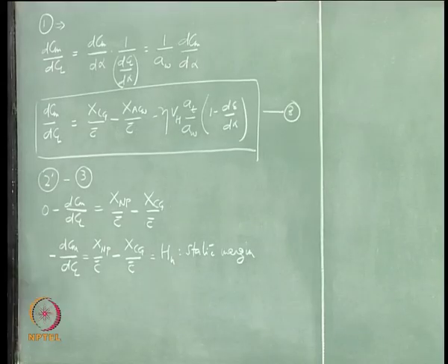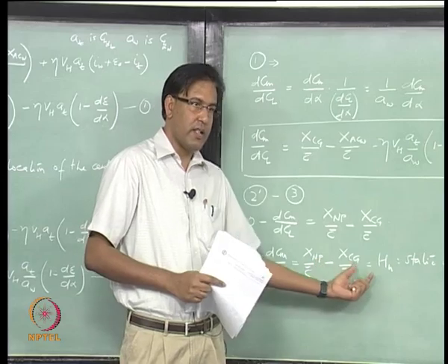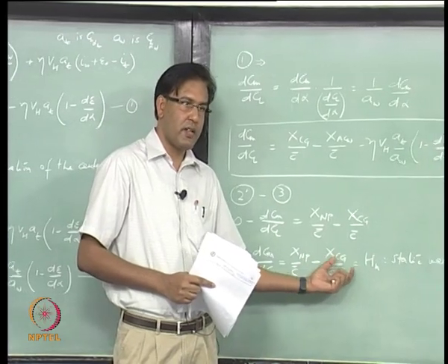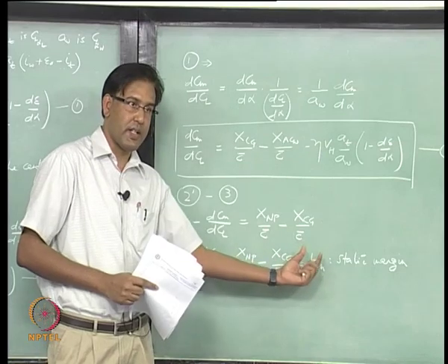From pilot's experience of flying conventional airplanes, it has been found that for good handling qualities of aircraft, this Hn should be 5%. Okay.